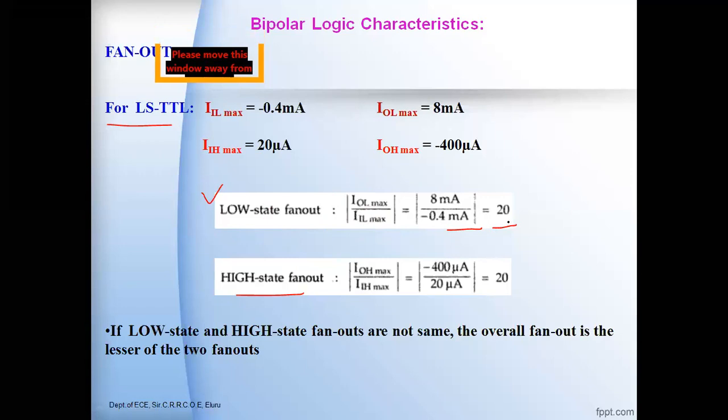The value is 20, which means that the LSTTL NAND gate during the low state output can handle a maximum of 20 TTL input gates.